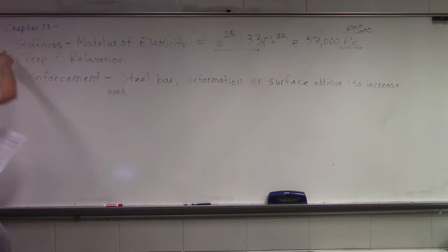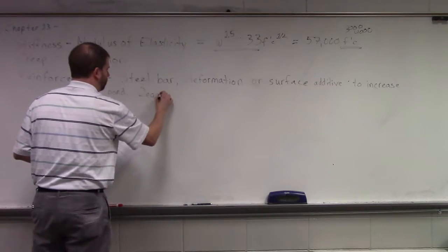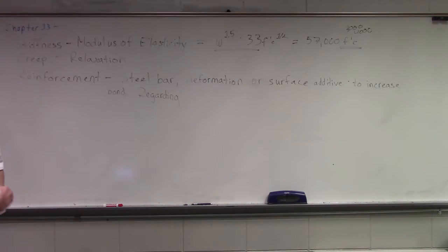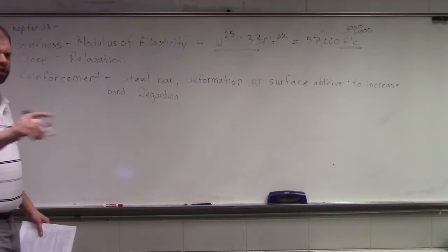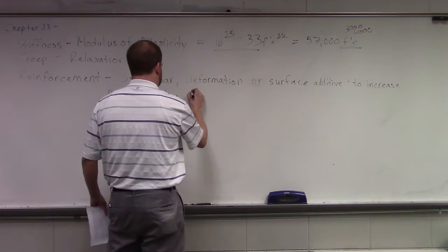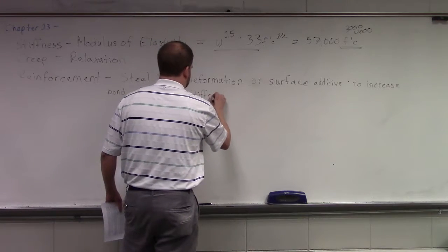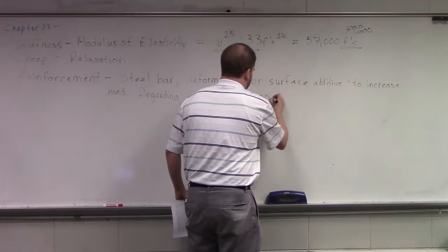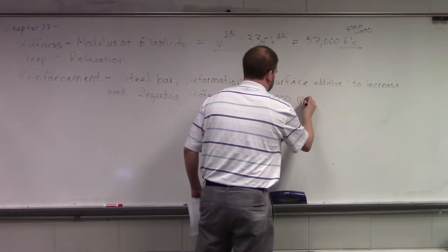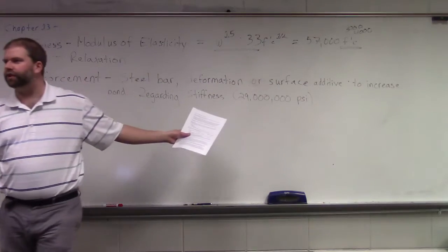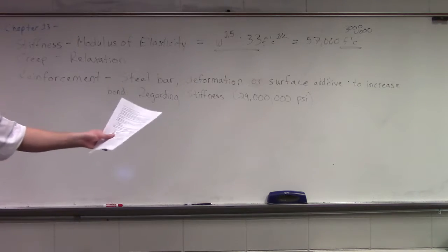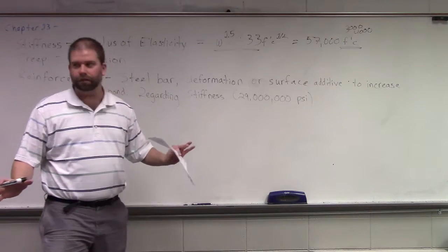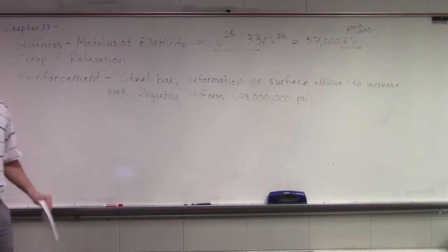Getting back to the stiffness. Do you remember what the modulus of elasticity is for steel? 32 million? No. 29 million, right? I was going to say 30,000. Well, you were thinking in ksi, right? So typically our modulus of elasticity with steel is about 29 million. We do not see that high of a number with our concrete. We're probably seeing 9 million, maybe 10 million, maybe 11 million. Kind of the limit of what we can produce currently.